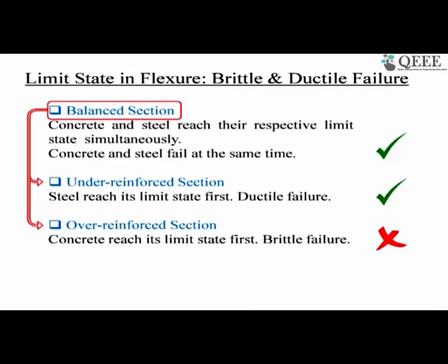How are the stresses determined in steel? We have not really done the analysis yet, so let us do the analysis first. But to answer your question, we calculate the strain first. We know the strain diagram. We calculate the strain first, and from the strain we calculate the stress from the stress-strain behavior. But this exercise we will do tomorrow when we analyze the section.